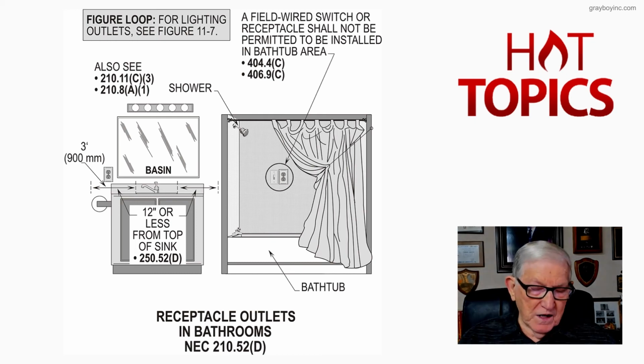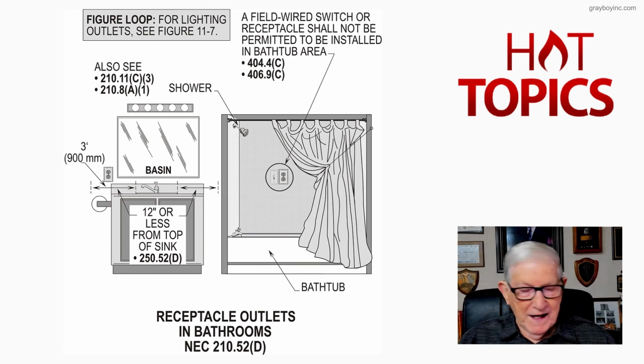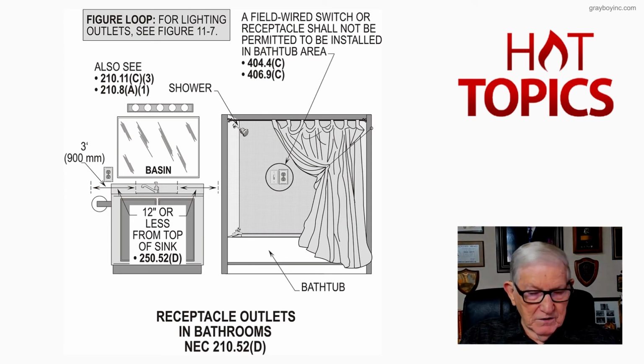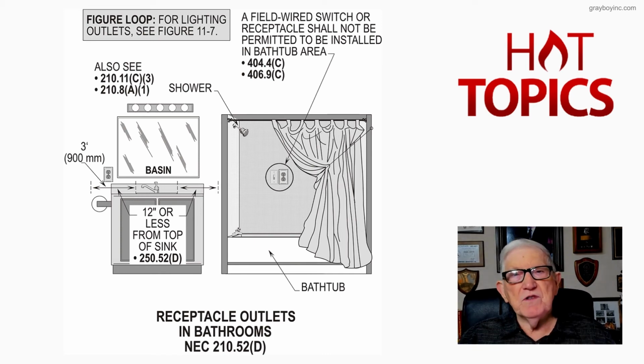And then, of course, I suggest very highly, and I think I have it written down here for you, look at 506.5(E) as in Ed, 506.5(G) as in gray, and that's on page 267 and 268 of the NEC, and then you get more information about these receptacles.